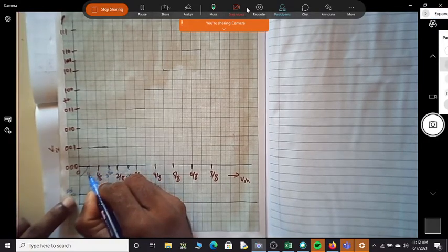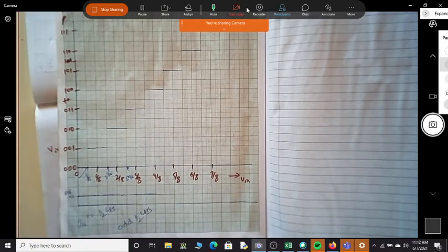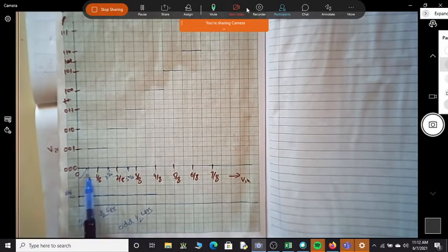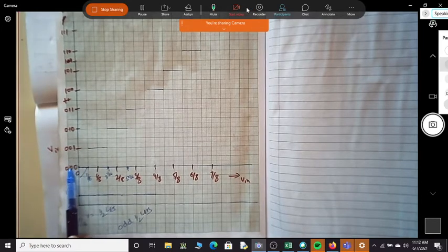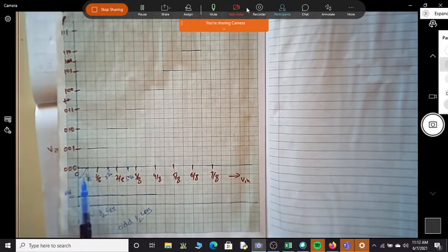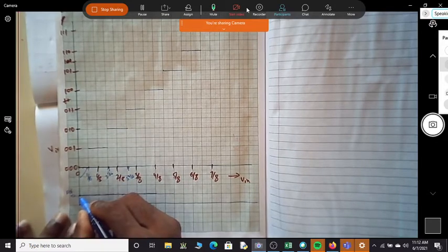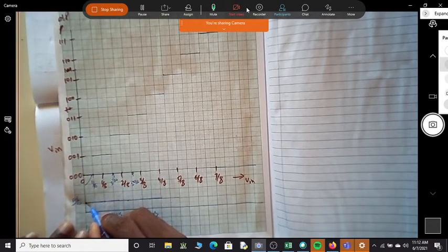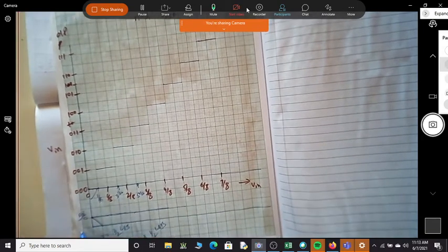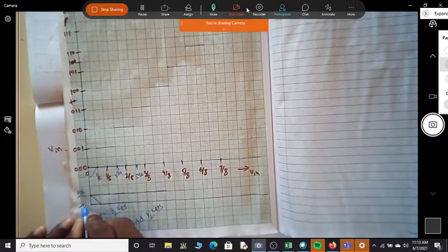Now the input voltage is 1 by 16. Are you still representing it as 000? Are we actually underestimating the input voltage? Input is actually half LSB. Your output is still stated as 000. You are underestimating the input by minus half LSB. So that is maximum over here. If I write this as my error, it is maximum over here. Is it minus half LSB?